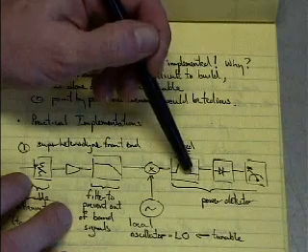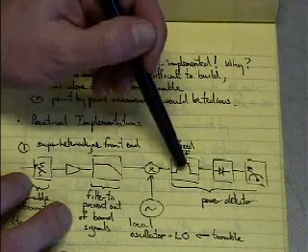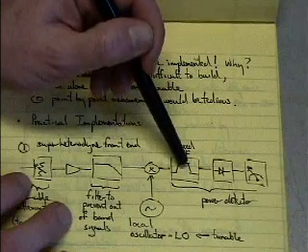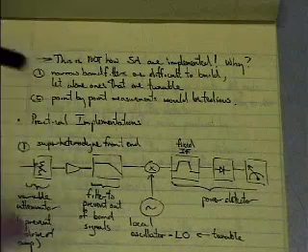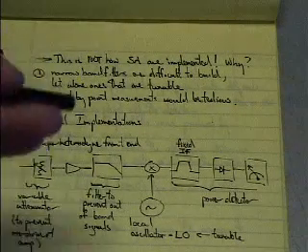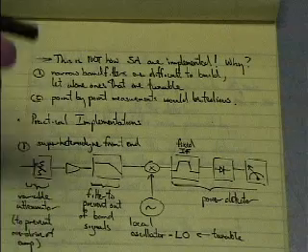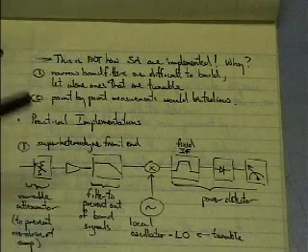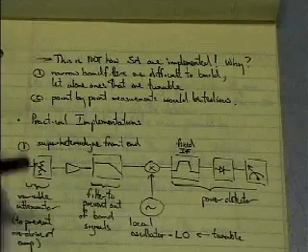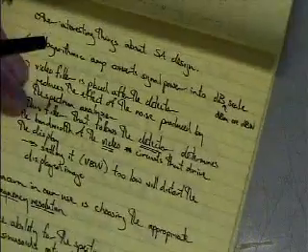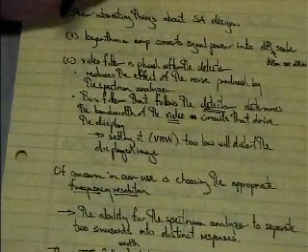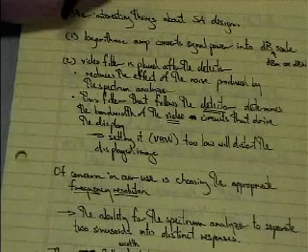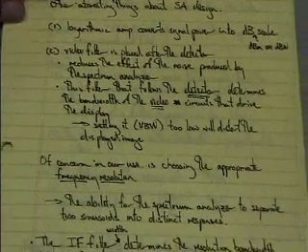As these two frequencies lie within this particular bandwidth here, they look as one to this filter. The filter can't tell which frequency is which, because they're both lying within the bandwidth. It's just going to merge both the powers into one signal. So you're no longer going to be able to tell that there are two signals there. Frequency resolution is an important term that we're going to be dealing with throughout the semester.